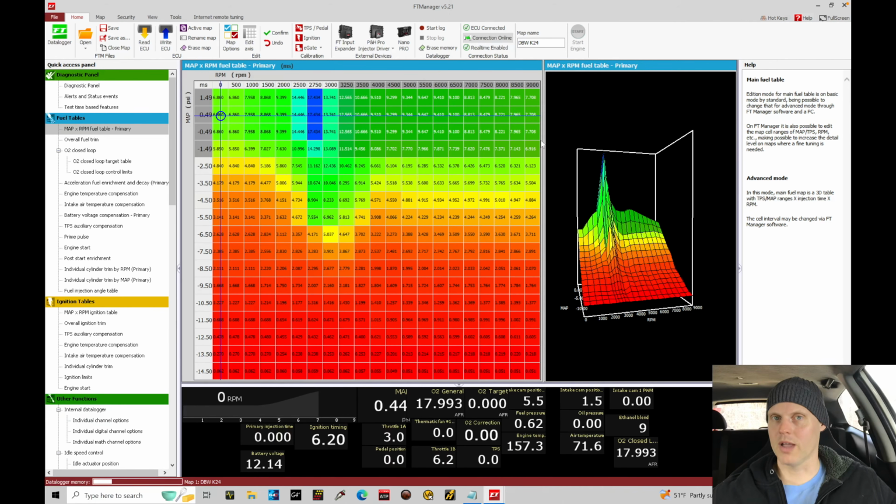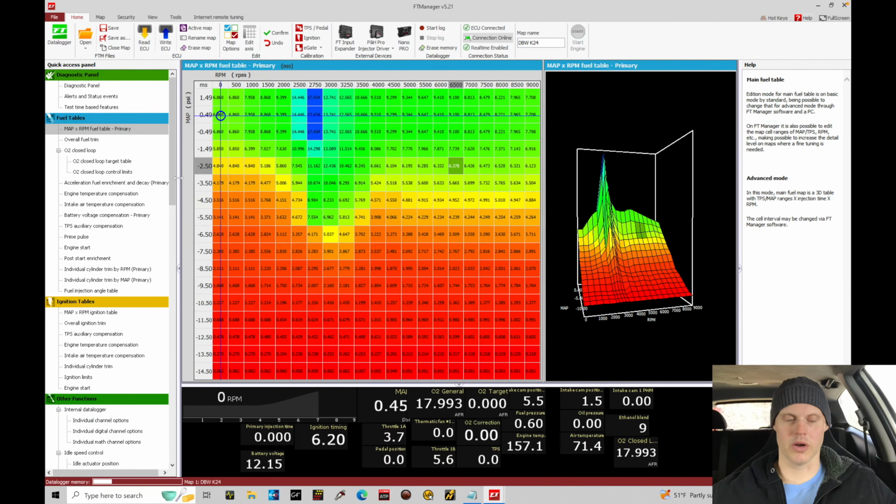So we'll dial everything in. We'll do our cam composite blend. We'll touch up our fuel table then. And finally, maybe adjust our spark timing a little bit, maybe 2-3 degrees at most. And that'll be it. All right, so we have everything in order here going down.